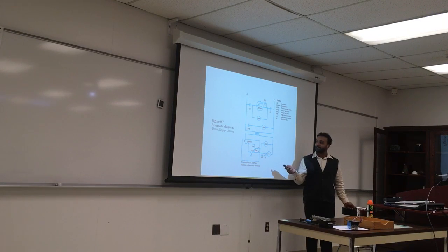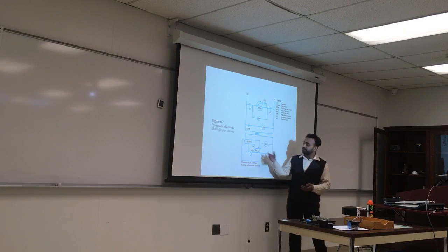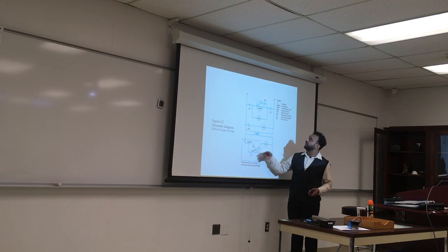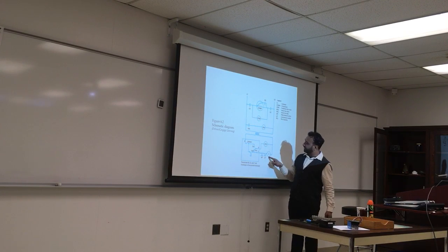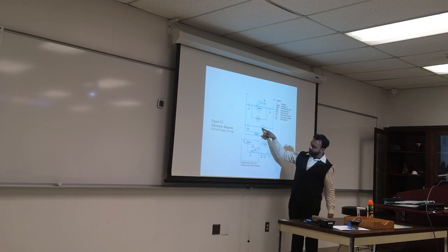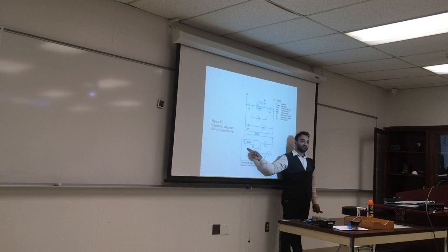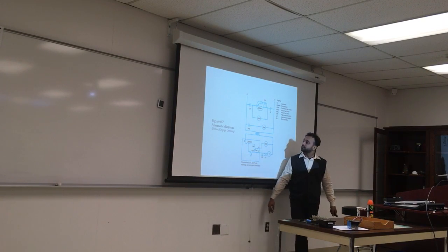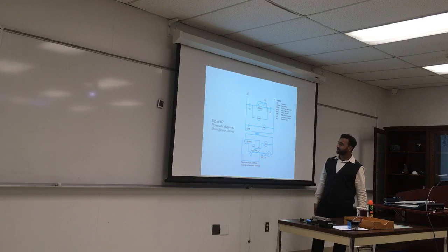Yeah, and this is the control board, right? This controls 24 volts and provides signals to close the contact here. And this relay will turn on the fan motor. And what is this box here? Thermostat. It's my thermostat. As soon as we identify each of those components, things will make more sense.